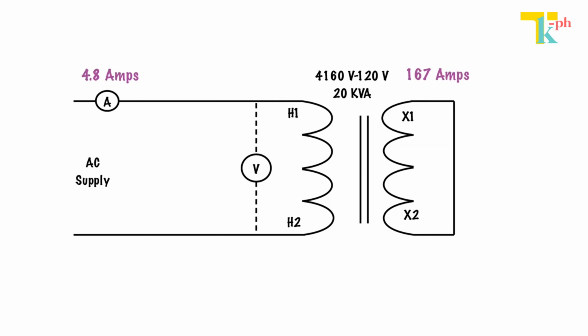This next calculation isn't necessarily necessary, but just to make the point that when we have 4.8 amps running in the primary side here, so if we have maximum current flowing in the primary side, we are also going to have maximum current running through the secondary side. Very important, because we have what's called a shunt bar here. Your shunt bar needs to be able to handle that maximum current, because we will be taking this guy up to its maximum current on the primary, which does mean that you will see 167 amps on the secondary. So it's just something that you need to be aware of.